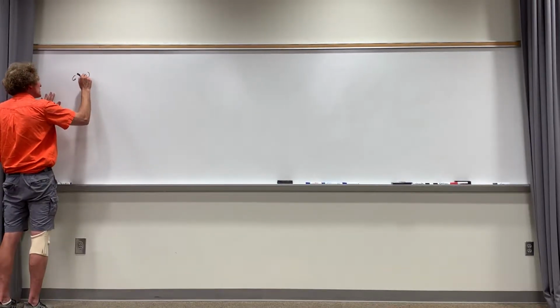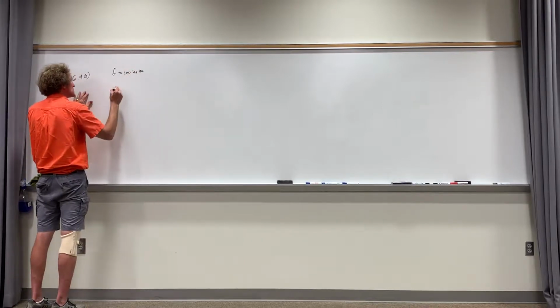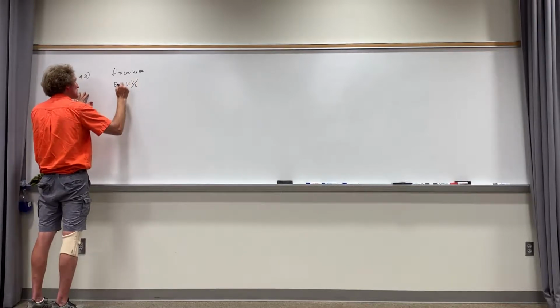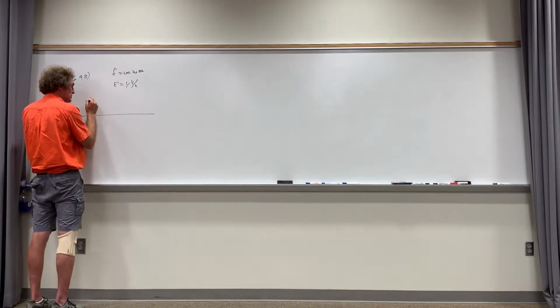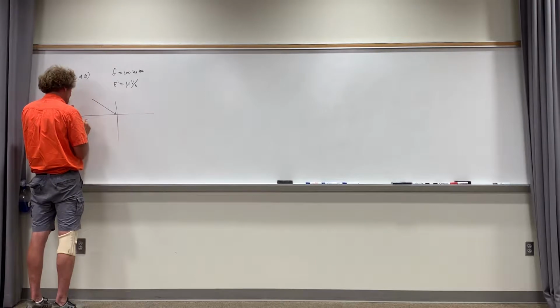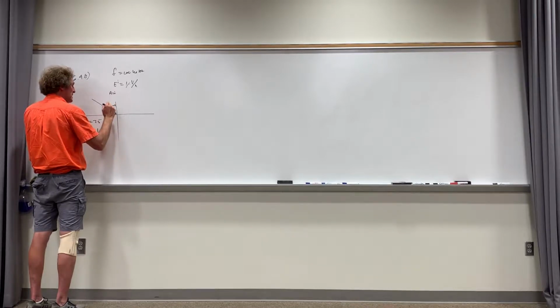It says a 100 megahertz TE polarized wave with amplitude 1 volt per meter is incident from air. 1 volt per meter, and that's E incident. Is incident from air onto a slab of lossless non-magnetic material with epsilon relative equal to 25. Mu relative 1? It doesn't specify. And this is air? Yes, sir. What angle is it coming in at? 40 degrees. 40 degrees, all right?